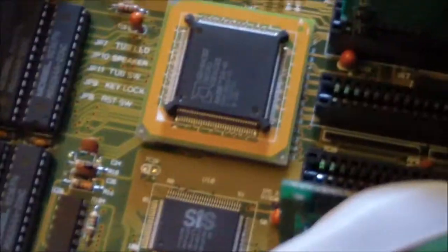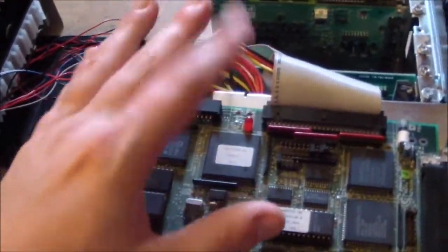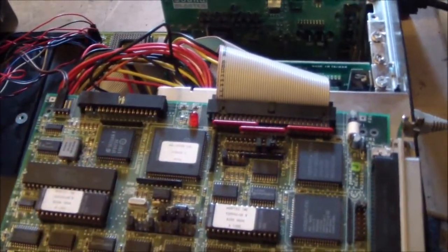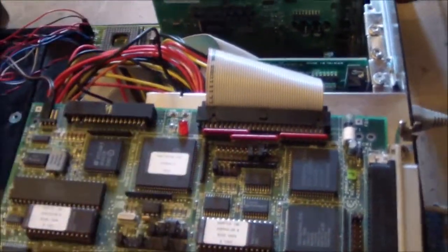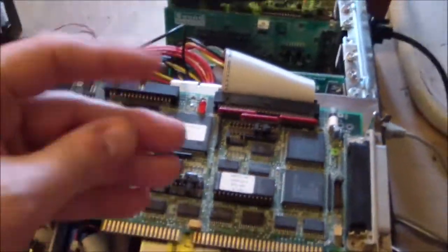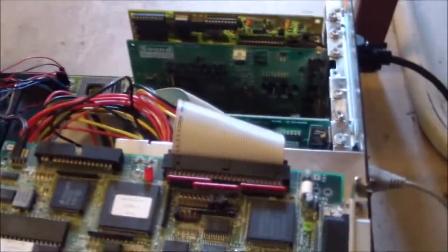So here's the first example of a SCSI device running in a setup. This is a very simple setup. The only thing I have running in here is the SCSI hard drive. Now this motherboard is a 386 board, an AMD DX40, nothing too fancy. Previously I had a 286 in here that I want to do a video on, but that board had the dreaded Dallas real-time battery issue where I couldn't get past POST, so I removed that motherboard. I might try the whole CMOS mod on that battery.